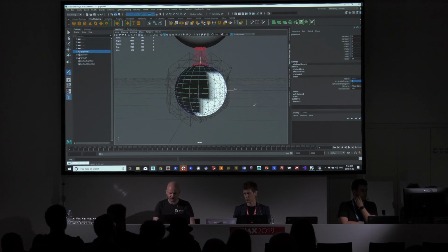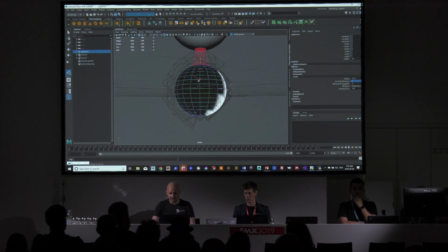Also, one other thing, in case it wasn't clear earlier, the resolution of the TET mesh really just has to be the right resolution to contain the deformation and the oscillations that you want. So a lot of times you can get away with really coarse TET meshes for things like muscles because they just squish and bulge. You don't normally see waves run up and down muscles unless you're doing high-speed photography. So you can get away with coarse TET meshing. All of the collisions, attachments, all those forces are applied at the surface that's embedded and get propagated out to the TET mesh. So you can decouple the concept of the resolution from how things are set.